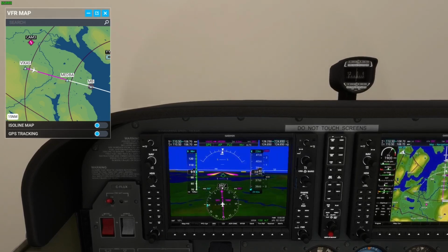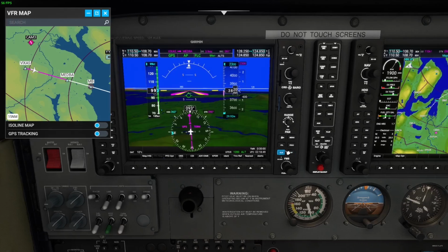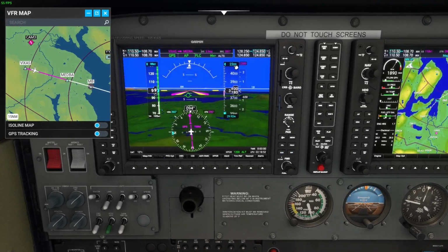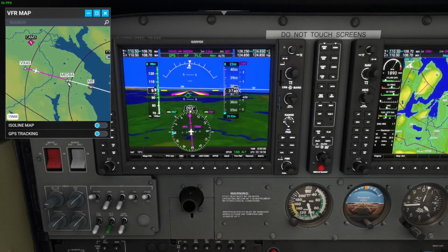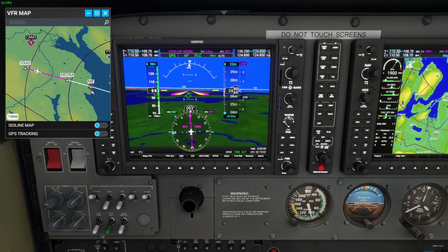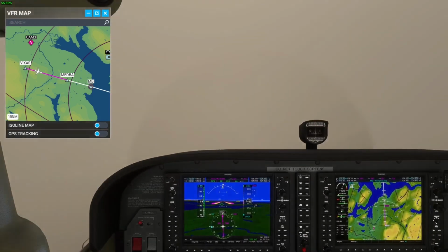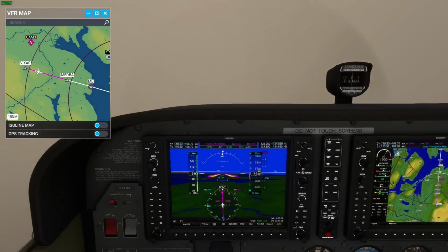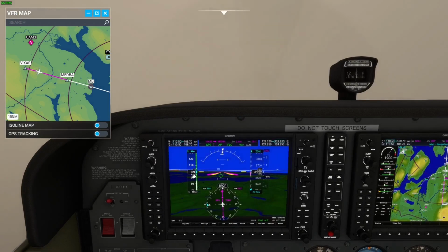Instead of when you're flying manually, where the throttle varies the vertical speed, now the throttle just works the airspeed, because the computer is doing whatever it takes to keep that vertical speed constant. You can also, by pushing another button, have it the other way around, where you maintain your airspeed, and by pulling throttle, change your descent rate. So it's up to the pilot's discretion.